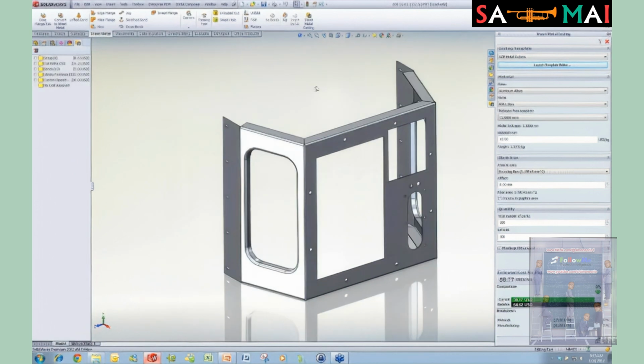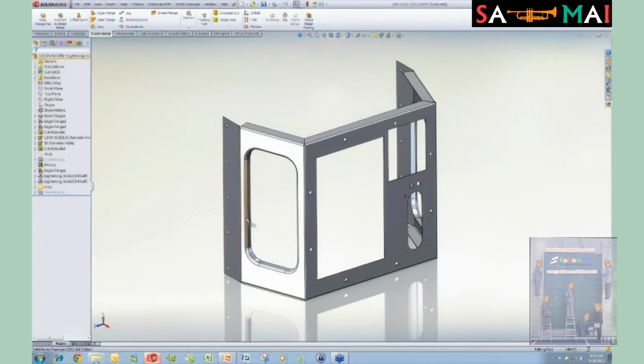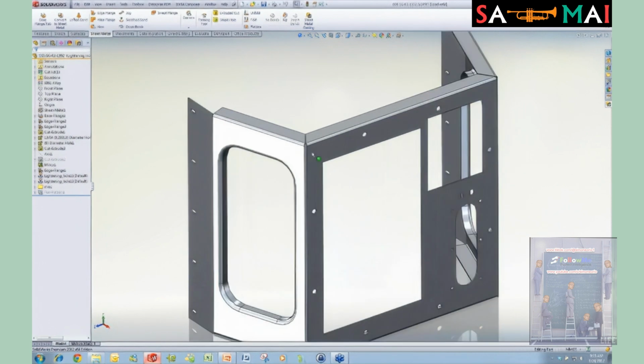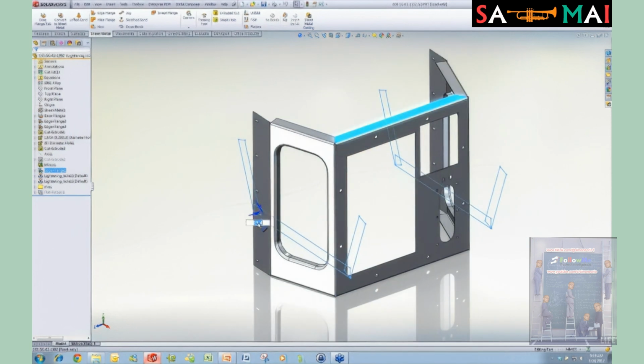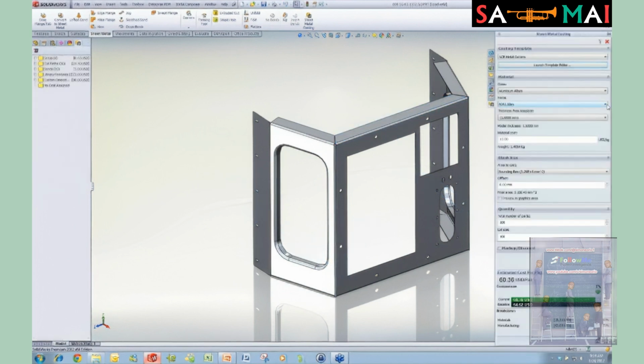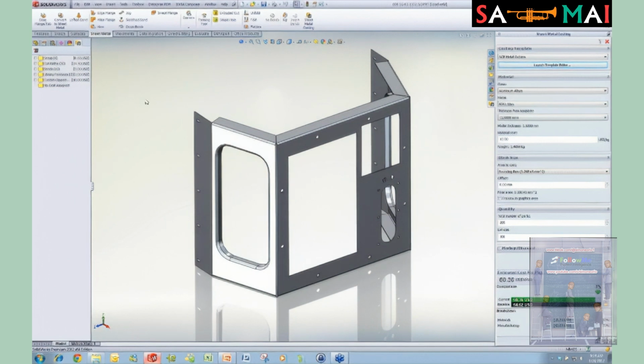We can unpin this so we don't see that all the time, and I can go back to my other tab here. We can spin this around to whatever I want. We can click on maybe different dimensions in here and change whatever we want. So 25.4, let's maybe make that that top edge. Let's go 30. So we'll increase the size. So we can go through and kind of design and work in this process, change things, and once it updates, we can go back to our costing and see what our price difference is. All right, now we're only at 7% increase or change from our baseline. So we can kind of work in that way.